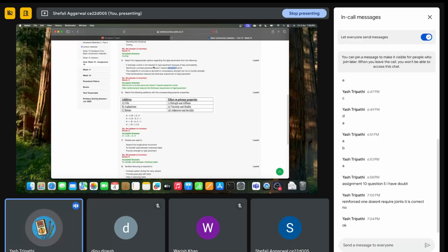And in non-reinforced one, we provide in both directions double cuts. No, dowel bars we were providing in RC structures only, RC pavements only. In RC pavements we talked about two types. You are telling about continuous RC pavements, right? In continuous rigid pavements, we say that we are not providing joints.